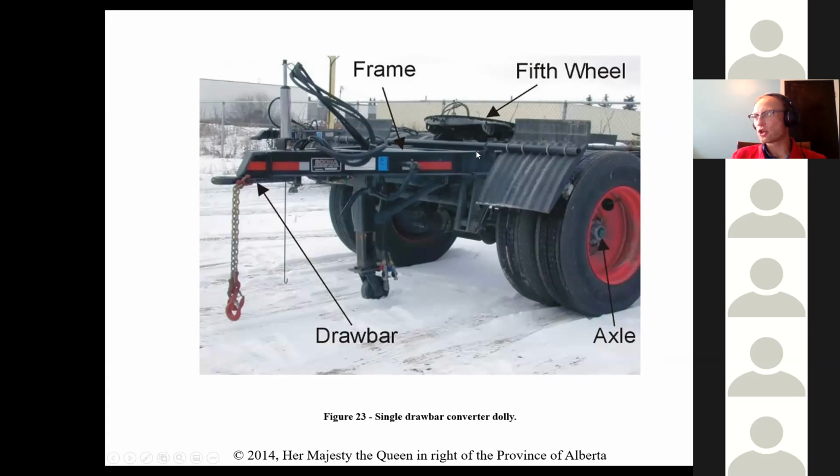I used to work at a dealership, and we would get converter dollies in, and you could fit 12 of them in one bay. And then when you would do a CVIP, you would just get all 12 pieces of paperwork filled out, one on every unit, and then you go around, all right, I'm going to check 12 5th wheels. And if one was out of adjustment, you'd mark it down on the corresponding paperwork for that one. And you'd finish all of them, checking PDIs, basically making sure everything works, connected properly, airlines aren't backwards, things like that. And then doing all the measurements for everything, right?